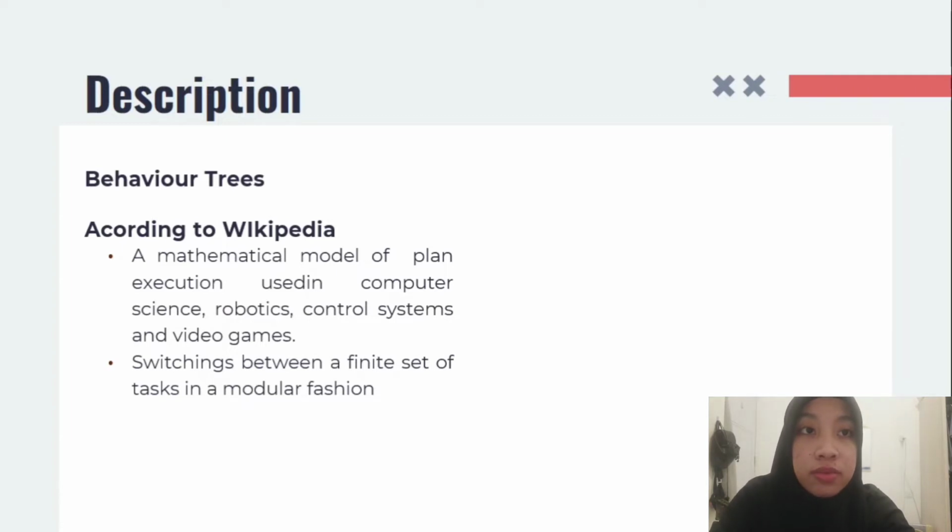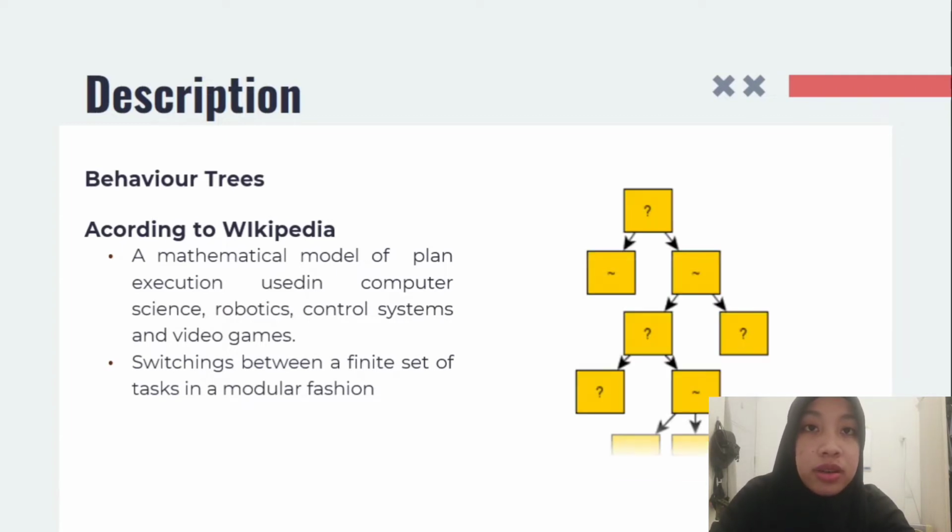Their strength comes from their ability to create very complex tasks composed of simple tasks, without worrying about how the simple tasks are implemented. Behavior trees present some similarities to hierarchical state machines, with the key difference that the main building block of a behavior is a task rather than a state.